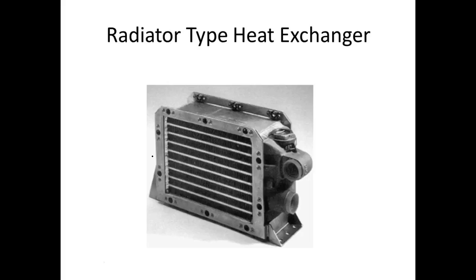So the fan is not copper. Copper transmits heat better, so it has a very low resistance path to heat. The formulas we use for heat transfer are exactly the same as we use in electronics for voltage, but here you have what they call thermal resistance.